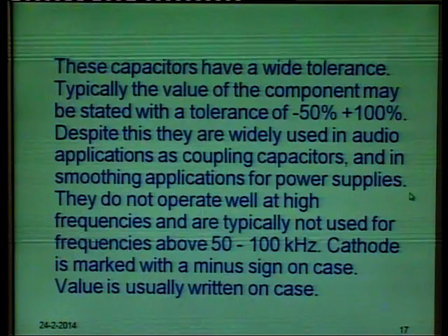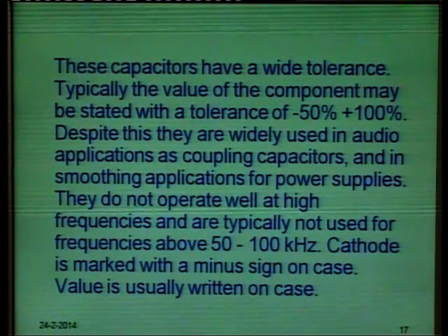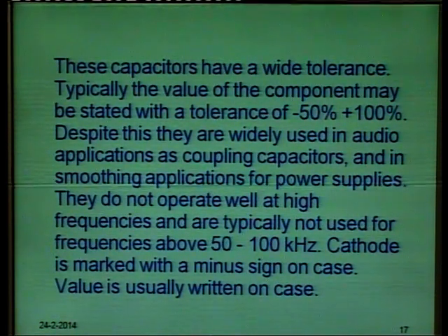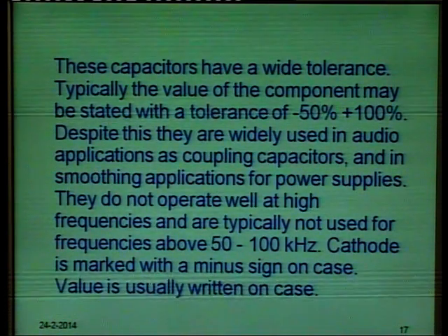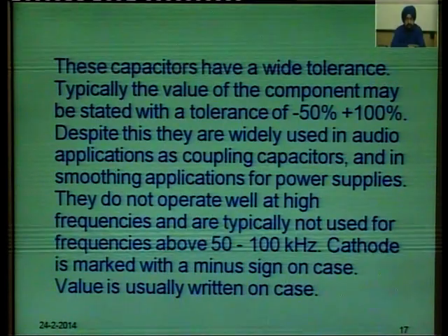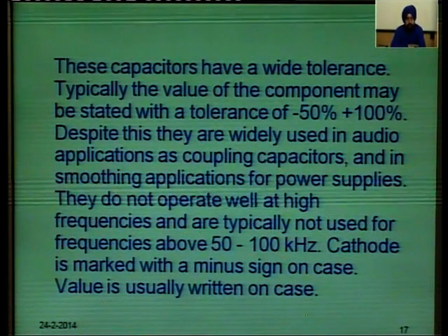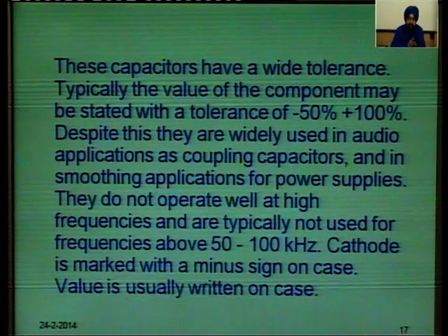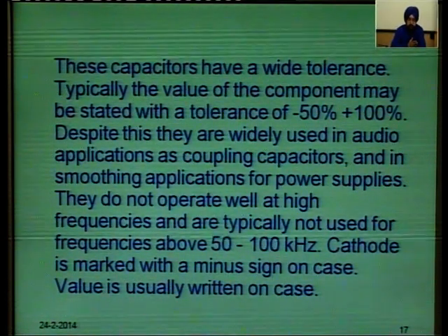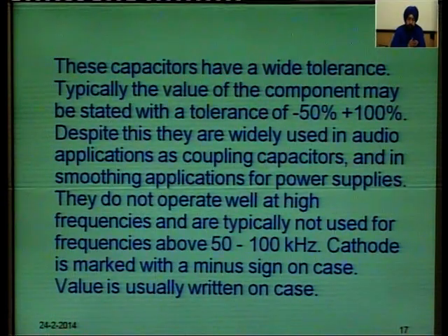These electrolytic capacitors have a wide tolerance. Typically, the values of the component may be stated with a tolerance of -50% to 100%. They are widely used in audio applications as coupling capacitors, and sometimes they are also used in smoothing applications for power supplies.